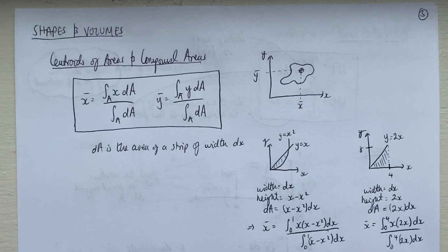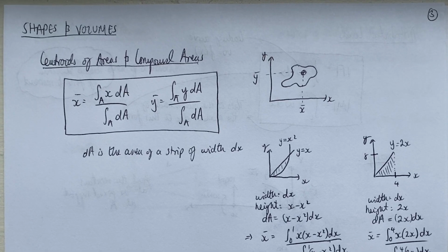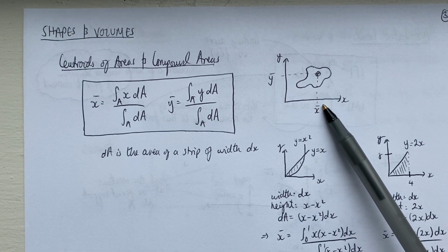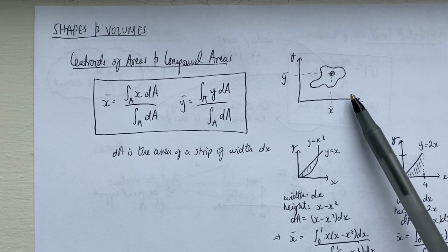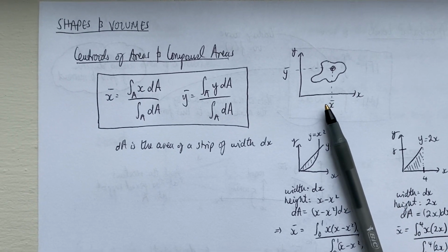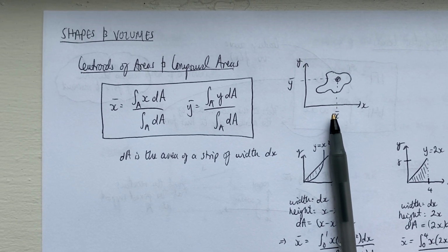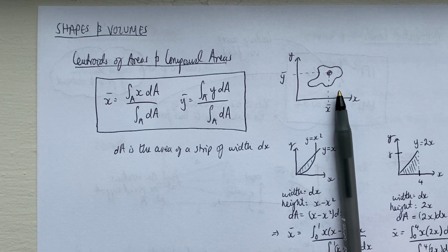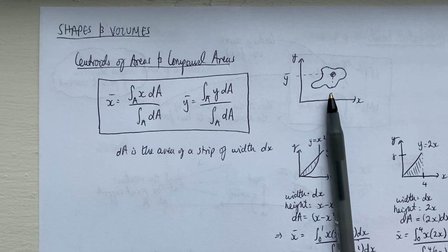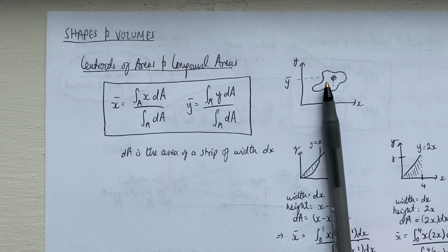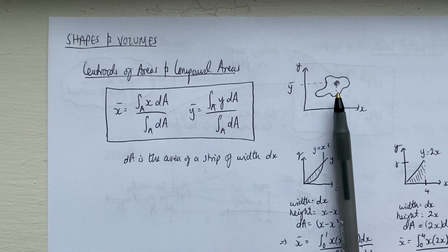So you'll remember I described this in terms of, let's take the x-coordinate of the centroid of the area of this blob. What we're finding here is the point where, if I place this shape on like a seesaw, like a fulcrum point, I'm finding the x-coordinate where the left-hand side would balance the right-hand side, right?